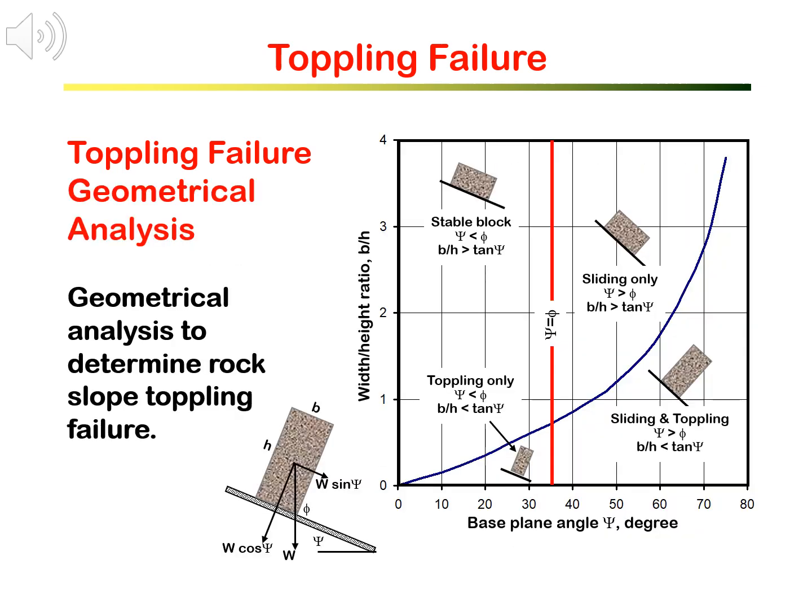As toppling failure is represented by tipping over, it is therefore governed by the geometry of the block shape and the resultant body force. As shown in the diagram analysis below, when the body force W is inside the width B, the block will not tip over. Only when the W line is outside the width B, the block will tip over around its base corner.